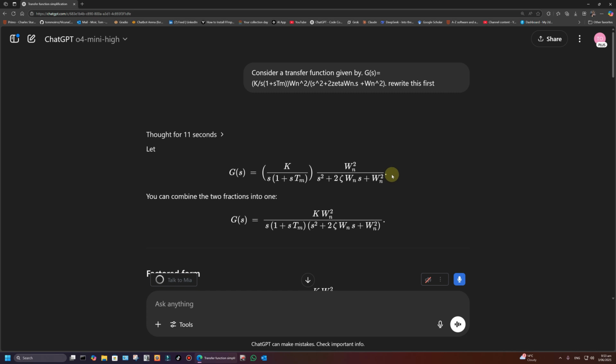The reason I put this in is because I've tried other examples without structural resonance, and of course they do that in many textbooks, including my own textbook. But in my textbook, I normally consider the structural resonance as well, because in real life you do have something that limits bandwidth. You can't have a control system with infinite bandwidth, because otherwise you can just define the unity gain point, the bandwidth of the system, to be any way you like. Whereas this reduces the chances of you doing this because of the phase, and I'll explain that in a moment.